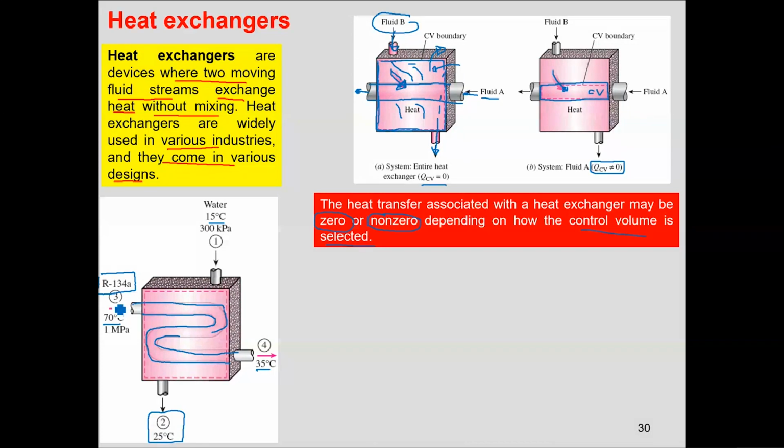to outlet 4. Now, if this is taking place, the mass flow rate at inlet 1 is essentially the same at outlet 2. That means whatever amount of mass flow rate of water is entering into the system, it is the same as it is leaving the system. So you can call it the mass flow rate of the water.